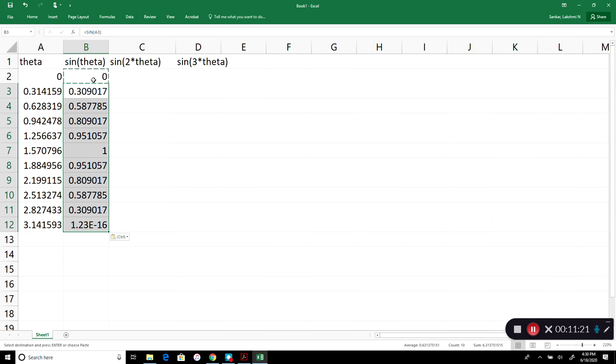Okay. So it goes, this is the wingtip. When theta is 0, it's the wingtip. When theta is pi, it's another wingtip. Again, it's very, very small. And when theta equals 90 degrees, we get the highest value, which is 1. And we see symmetry. That means this number is equal to this number is equal to this number. So the left side of the wing and the right side of the wing will have symmetry, same loading. So there won't be any rolling of the wing or the airplane. So it's a good term to keep.